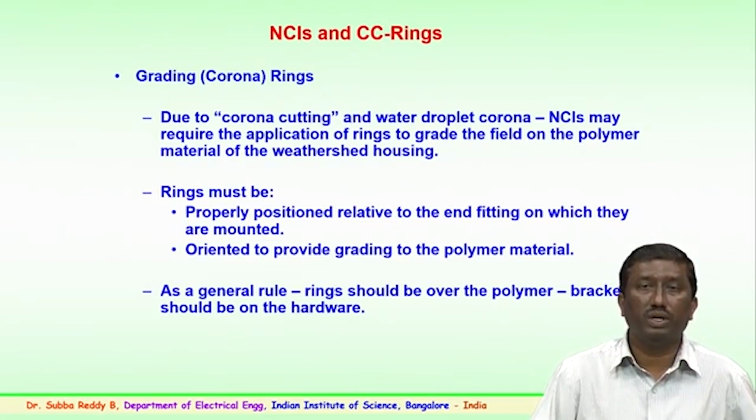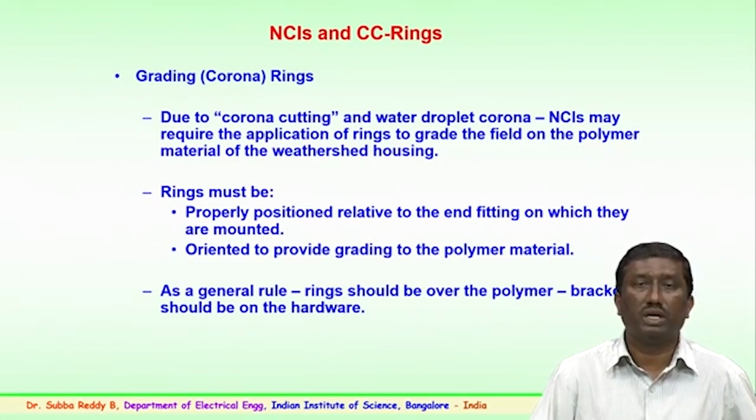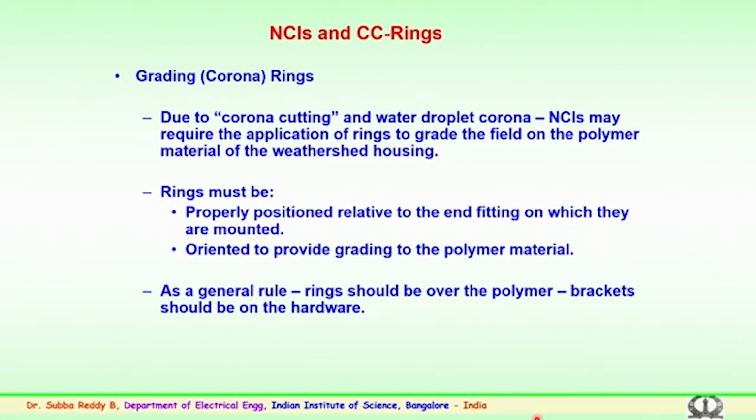Non-ceramic insulators have different corona control rings, which are designed differently from those for porcelain or glass insulators. Here the design of the grading rings or corona control rings depends on how the hardware end fittings of the non-ceramic insulators are designed, and on the particular voltage level.